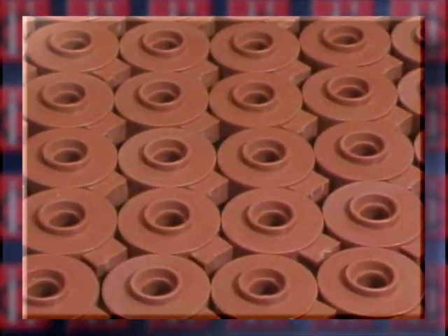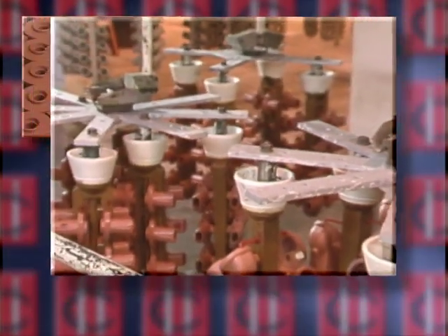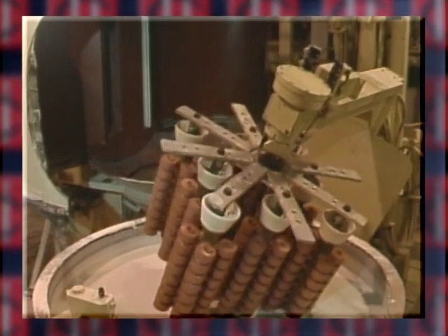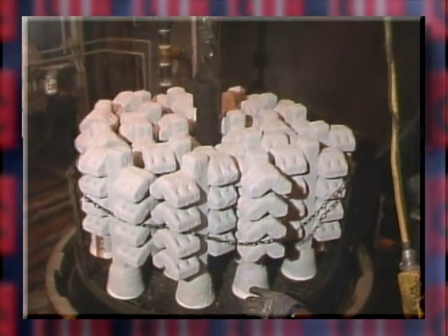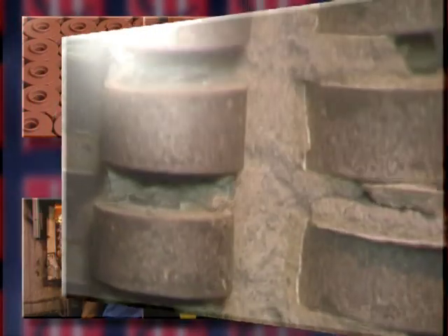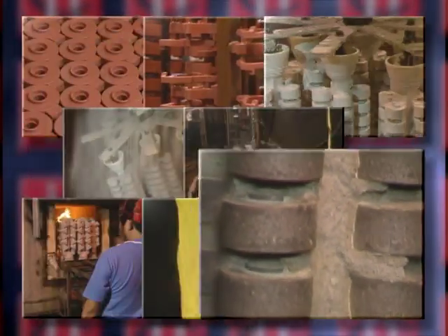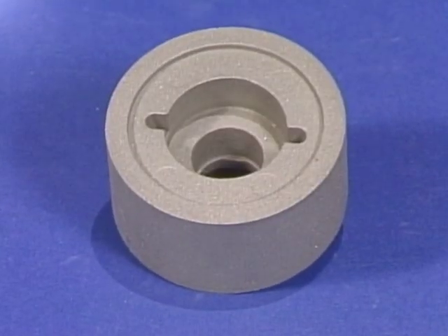In summary, the investment casting begins with a wax pattern made by using a die. The pattern is mounted with others on a tree or assembly. Next, the assembly is given a fine pre-coat of stucco, followed by several coarser coats of stucco. The wax is removed in a steam autoclave and the ceramic shell fired. The molten metal is poured into the shell by a transfer ladle. After cooling, the ceramic shell is removed by vibratory methods and the finished casting appears, looking exactly like the original wax pattern.